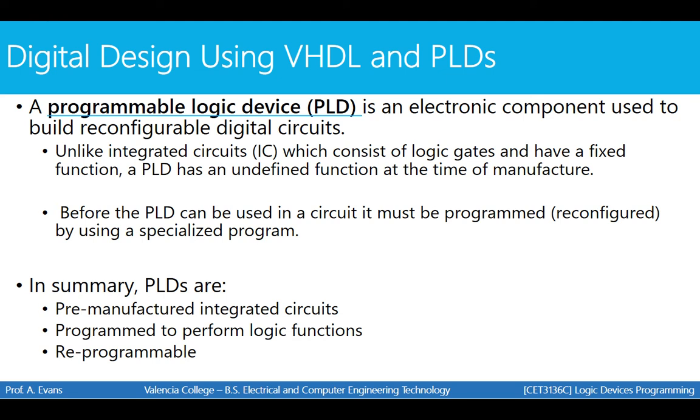So in summary, PLDs are pre-manufactured integrated circuits that can be programmed to perform logic functions, and then they are reprogrammable. So each time you program something to our Max-10 board, that board will execute your code as long as it has power. Once you disconnect the power, your code will be gone, and you'll have to reprogram it each time you connect your circuit board to power once again.